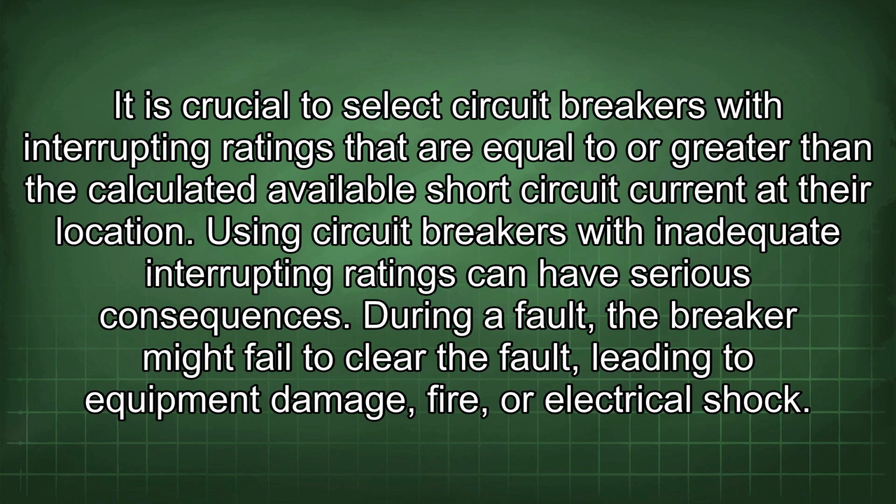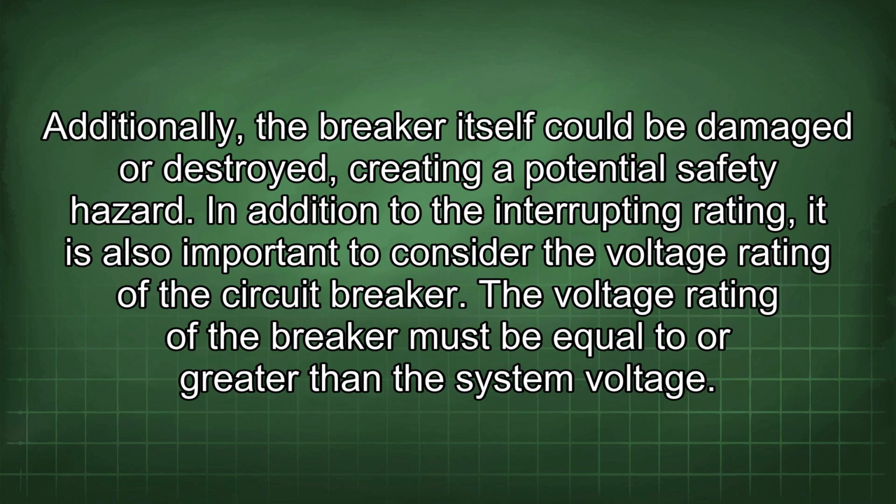During a fault, the breaker might fail to clear the fault, leading to equipment damage, fire, or electrical shock. Additionally, the breaker itself could be damaged or destroyed, creating a potential safety hazard. In addition to the interrupting rating, it is also important to consider the voltage rating of the circuit breaker.